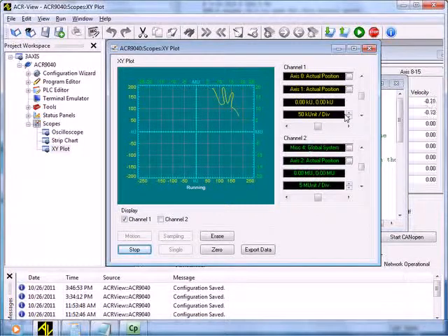And there's the thumb. Congratulations on writing your own NURB program. The cubic spline interpolation fits a smooth curve, exactly passing through the data points specified by the user. The data points can be non-evenly spaced. This is based on the clamped cubic spline algorithms, thus allowing the user to specify the initial and final velocity in the algorithm. Interpolation, like the NURBs, can be time-based or velocity-based.